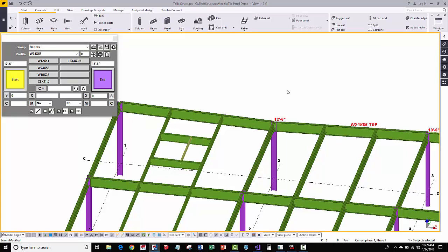If you imagine all the time that it would have taken for you to lay in points or vertical construction lines and offset this, or even put in magnetic construction lines and try to move things around, this is just much faster. You just pick the pieces, press modify, and it does all the searching and slopes the framing for you.